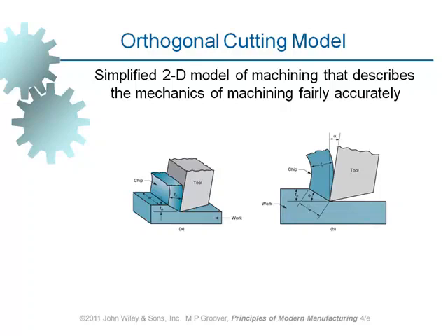Say, for example, 5 millimeters depth of cut. You can take 1, 2, 3, and the very final pass, which is the finishing operation, could be about 1 millimeter or so in order to achieve a good surface finish. But if we want to take a depth of cut of 50 millimeters in one go, it's impossible. So you can distribute it to a number of passes.